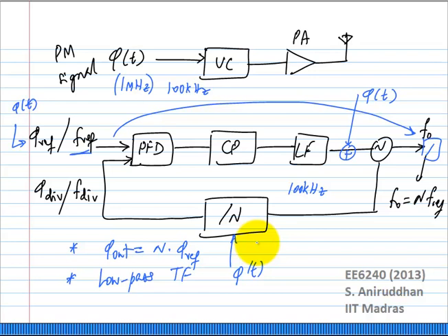So in that case, it may be a lot easier to actually just supply the data through the division ratio. Maybe to get the output frequency to a particular accuracy, you had, let us say, 18 bits of division ratio, integer plus fractional, to actually allow me to select intermediate frequencies also.